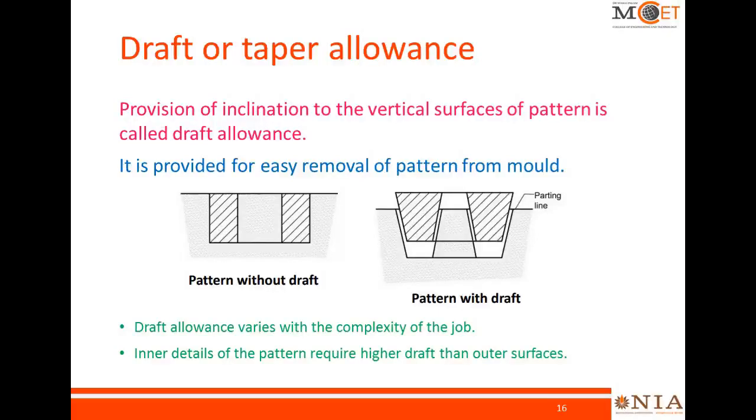So for the first case, when you try to remove the pattern from the mold, there is a chance that the mold cavity is getting damaged. But in the case of a pattern with draft, if you provide a draft allowance, it will be easier to remove the pattern from the mold. So for easy removal of the pattern, we have provided draft allowance, which is also called taper allowance. You can see here vertical surfaces are given some taper so that it will be easier to remove the pattern.